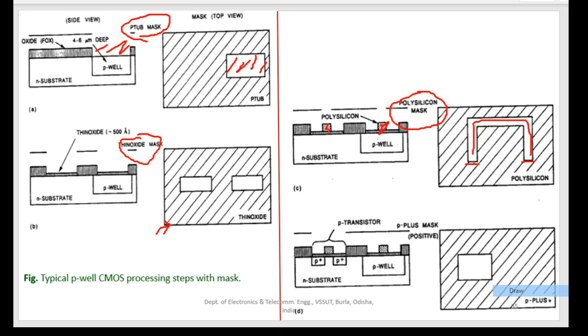It looks like this from the side. Okay, and these two have to be connected to a common point, and hence this is connected to this particular gate of NMOS. Okay, and that's why it is in this continuous fashion, it is not disconnected. So this particular mask will be used for fabricating the gates of PMOS and NMOS.